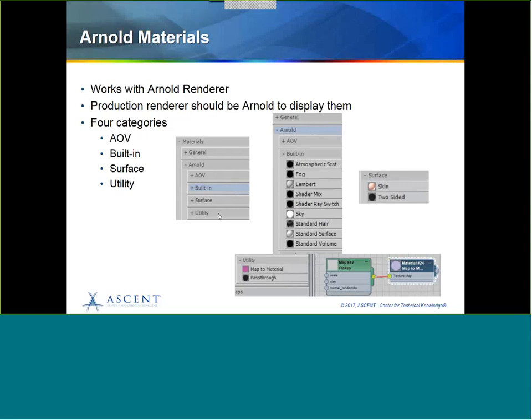These are used when rendering a scene for compositing. Now, those of you who are familiar with compositing will know that it's very useful to separate out various elements of the rendered image. For example, you want to have a separate diffuse path and a separate reflections path. This way you can make changes to individual passes only. These images are called AOVs. You can combine those at a later time.